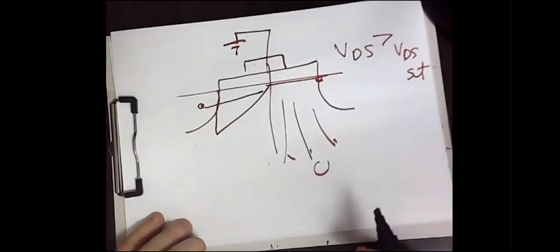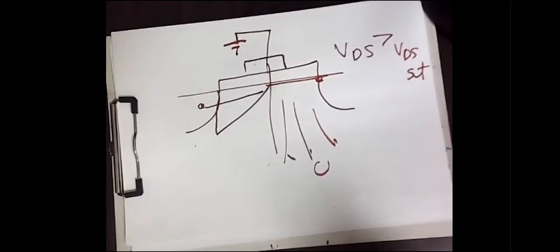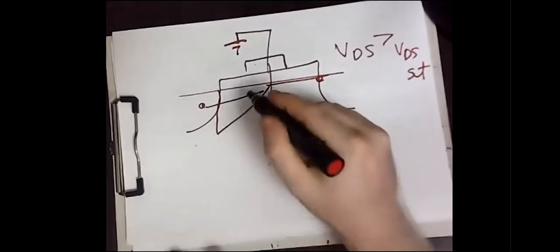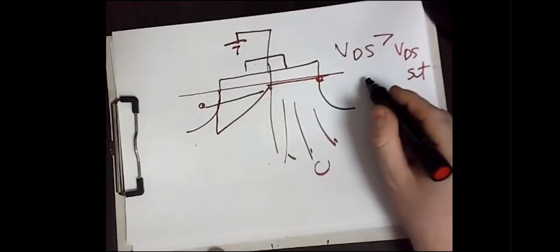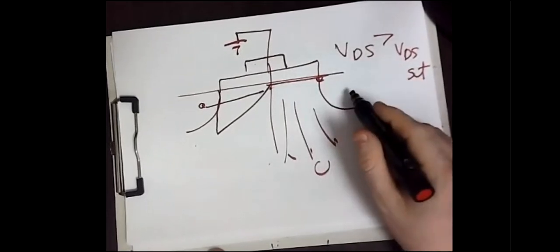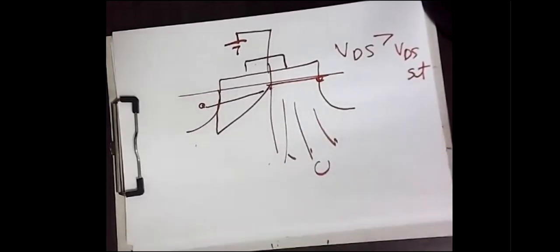If you remember, the depleted region is a region with a very high resistance. It's some sort of insulating material. So once the electron reaches this point, it will only pass the barrier or the depletion region because of the very high attraction force due to the drain. It's something like a tunneling effect. The electron tunnels this depletion region at a very high velocity.